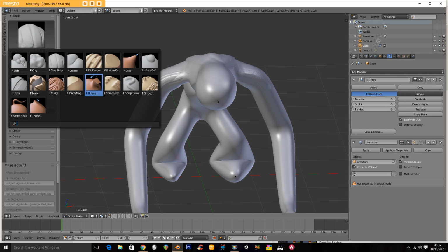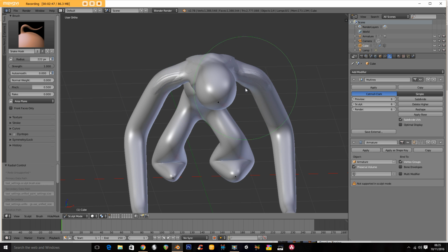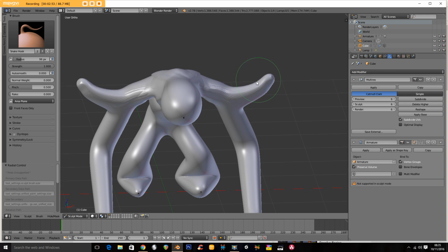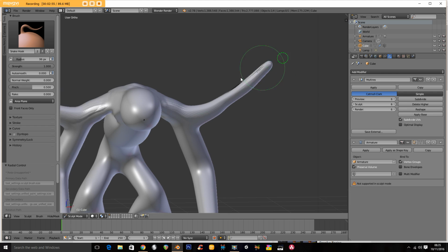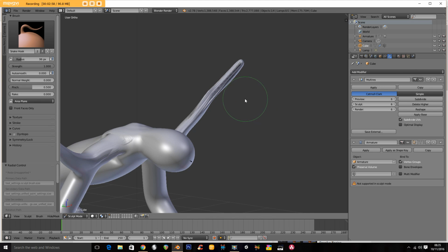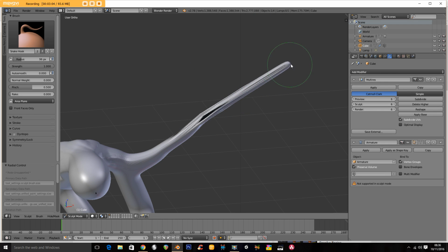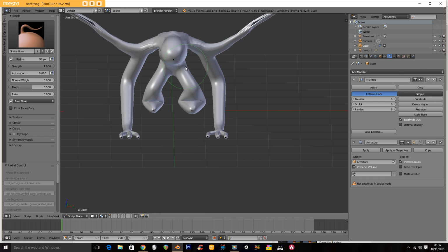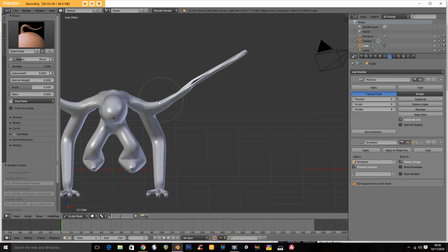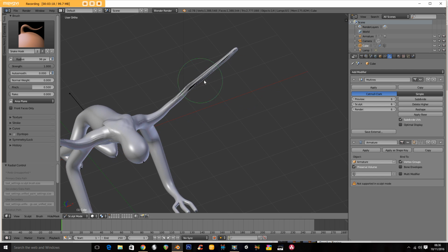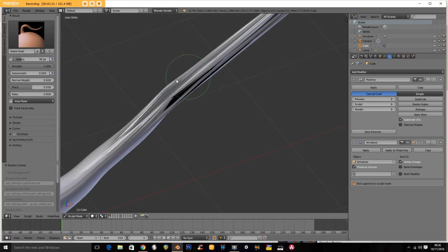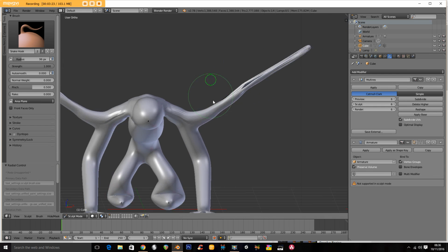Also, if I take a hook tool, I can start taking this away. This looks fine now, but if I keep doing this, you'll see the vertices start to stretch. Even though there's 1.4 million of them, as I stretch them out, that 1.4 million is spread out over the whole model. So if I just picked one patch of maybe 1,000 and keep stretching and stretching, eventually I'll get down to hundreds of vertices and then individual vertices, and I'll get distortions and anomalies that look like this, which are not desirable. So how do we get around that?